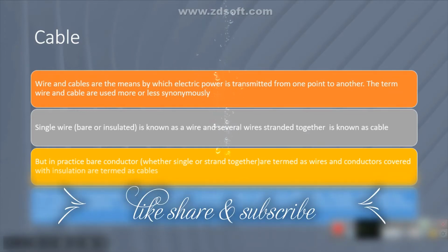Friends, this point shows us a capability or a minimum criteria that your conductor needs to fulfill so that you can use that conductor for installation. The minimum criteria are to conduct electricity efficiently, cheaply and safely. Its insulation should be such as to prevent leakage current in unwanted directions, and the conductor you have selected for your installation must be able to minimize the risk of electric shock and fire.